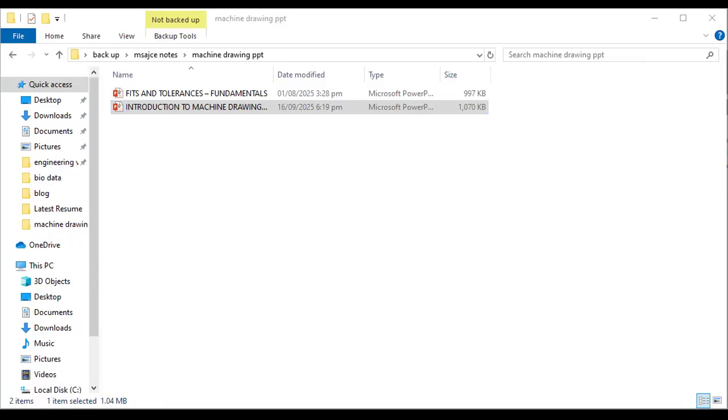So, drawing sizes and layout. Normally, the standard sheet preferred for technical drawing is A2. Here we can arrange all the basic information related to engineering drawing, including the title block, borders and margins, etc. The next one is defining the scale ratio for the object to be drawn on the specified area over the drawing sheet.